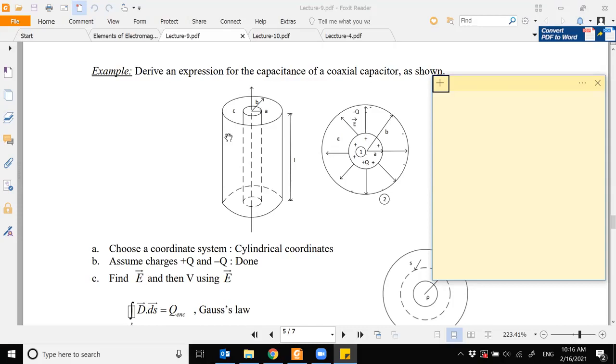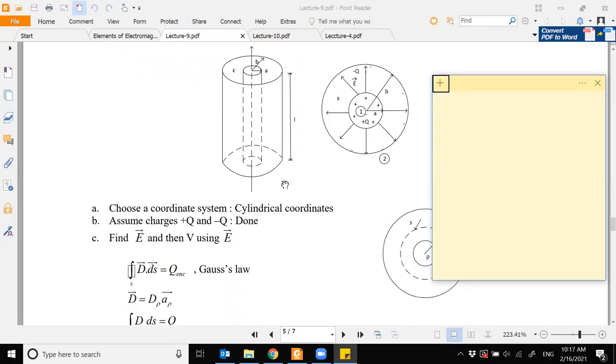The resistance is small, so therefore the attenuation of your signal will become less, and the capacitance, which creates a filtering effect, the smaller the value of the capacitor, the higher the frequencies that you can take through your coaxial cable. So this is what we are trying to determine here. And now you can see why electromagnetics is so important, because with the help of electromagnetics, you can find this capacitance and this resistance.